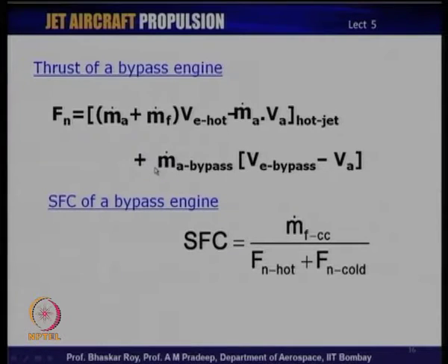So, in the second thrust producing component here, the mass of air that is being activated through the bypass system, or bypass cold jet, is indeed very high, and that is what produces a very high cold thrust from the second component. Whereas, in the first component, as we know, it is the V e hot which is the most important aspect of thrust production, because the mass flow there being processed is not of very high order.